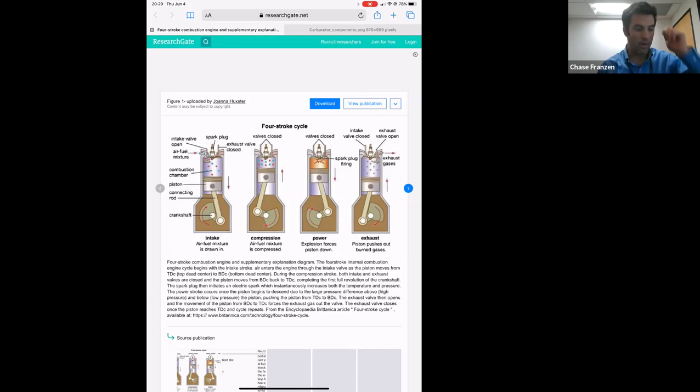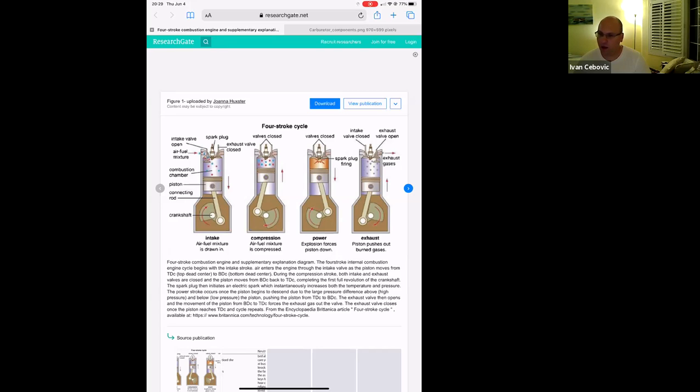Sure. Yeah. If you were to have fuel in one of the cylinders, and you had the magnetos ungrounded, so if your key was in and turned to one or both, and you were to apply power to the propeller via your hand, if you were to hand prop the propeller and get it started to turn, that's going to turn the crankshaft. The crankshaft is going to turn the magneto. The magneto, again, it's a coil stack with a magnet, is going to turn the magnet. It's going to produce power. It's going to fire the spark plugs. And again, as long as there's fuel and air inside of there, it will actually start the engine. Okay.